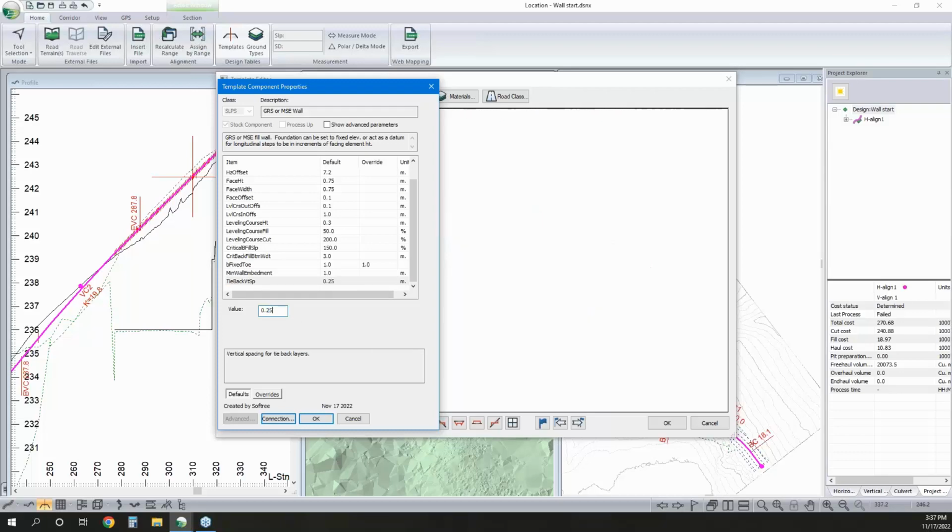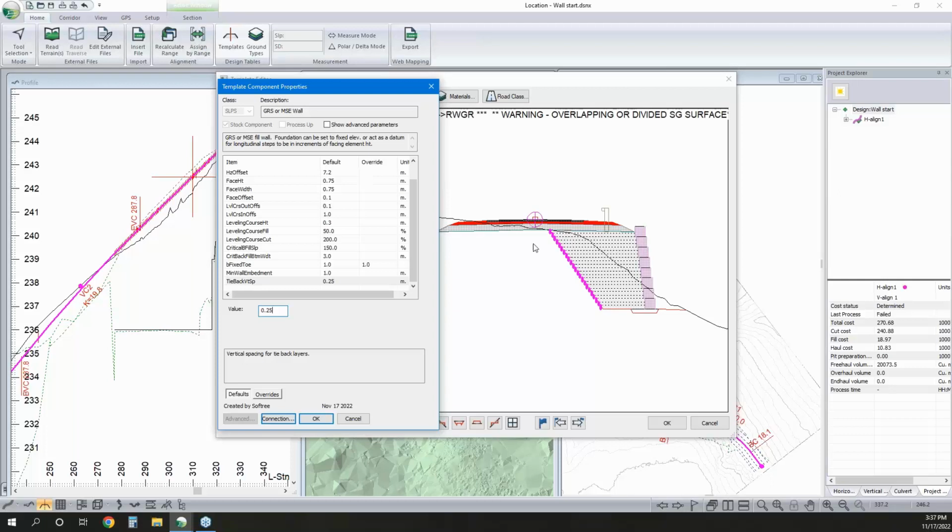So we've got that set to whatever we'd like, so we get the layers in between the facing units. Typically we do that in something that divides that neatly, so 0.25, 0.375, etc. If we want to have something right on the joint between those, rather than just saying how many per facing unit.